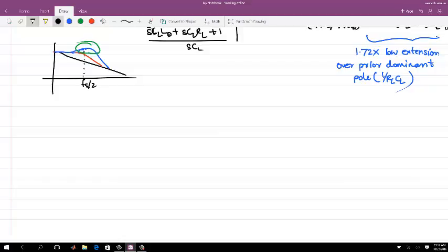Here you see, if you want to increase the DC gain, you increase RL. You increase RL, your peaking frequency comes in. That's what it is: VCM out and your peaking frequency are coupled. Or you basically increase the GM, so you have more power consumption. In this particular CTLE, once you have given the output common mode voltage, you are dependent on your RL and I for the current.